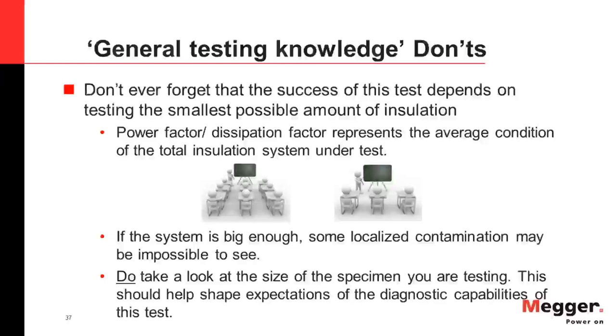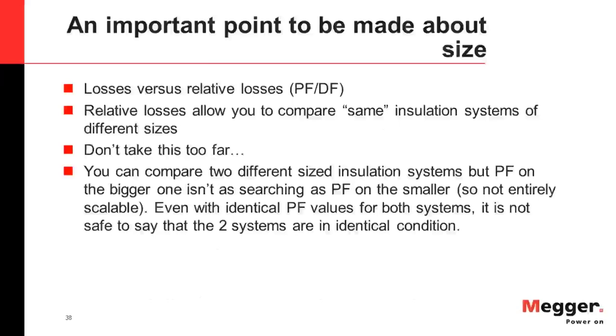Which brings me to a very important point that needs to be made about size. We've talked about the use of power factor instead of losses because relative losses allow you to compare same insulation systems of different sizes. But be very careful not to take this too far. You can compare two different size insulation systems, but remember that power factor on the bigger one isn't as searching as power factor on the smaller one. So it's not entirely scalable.